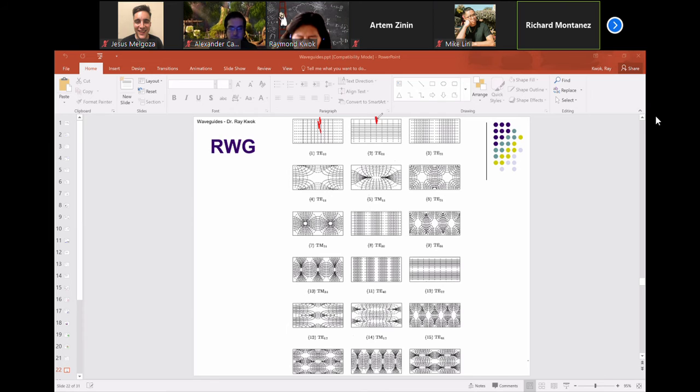I wouldn't think so, because this is the dashed line. Those are the magnetic field, not the electric field, so you cannot pick it up. Can I excite this mode? Probably not, because if you put it at the center, this is 0. If you pick up anything, because it's off center, you might see a small peak, but typically not. This is up, this is down, this is 0. So by putting a connector here, you will not be able to pick up a strong signal for this mode. Would I be able to pick up this one? Yes, this one, yeah.